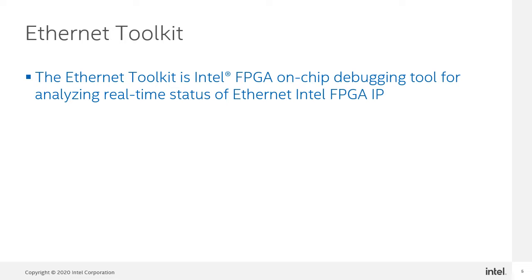Is there a problem with your reference clock? Is it a protocol implementation issue? Has your IP core been configured the way you expected? Is your application communicating with the IP core correctly? Has your partner device done an illegal operation, or are you receiving poorly formed packets?